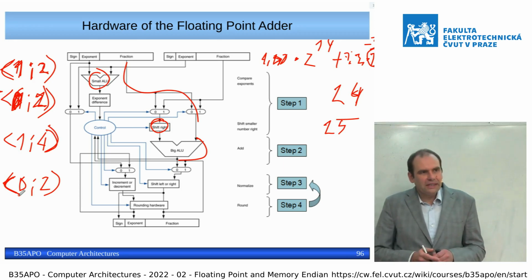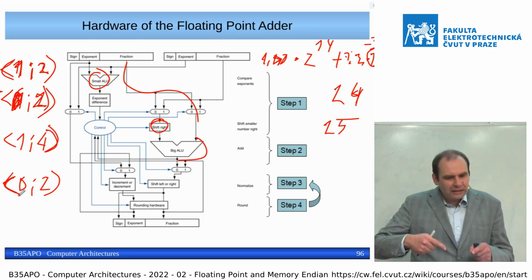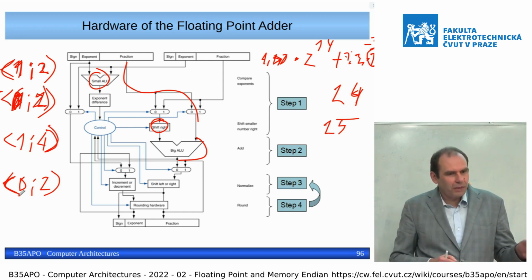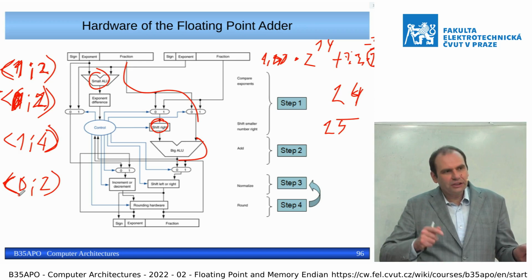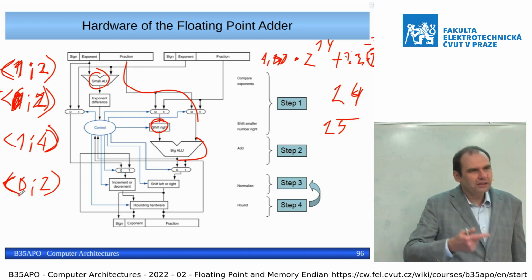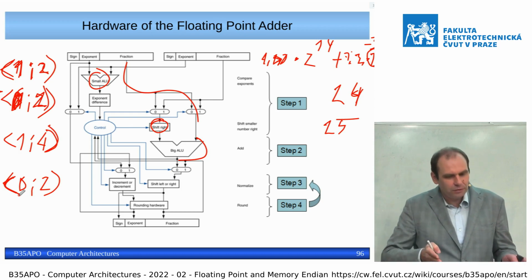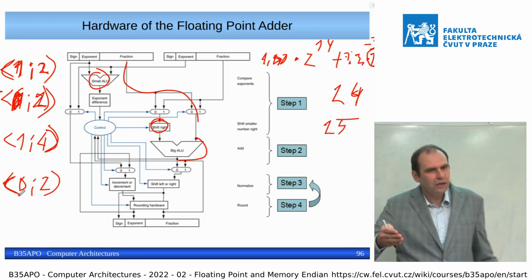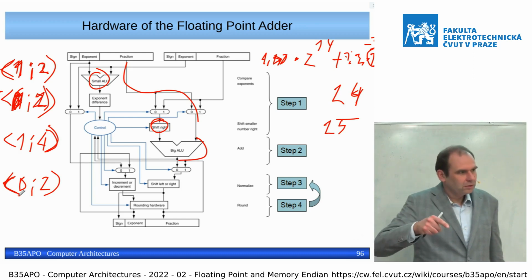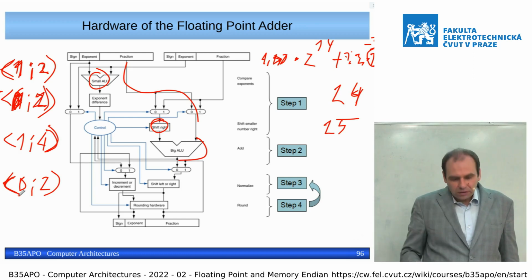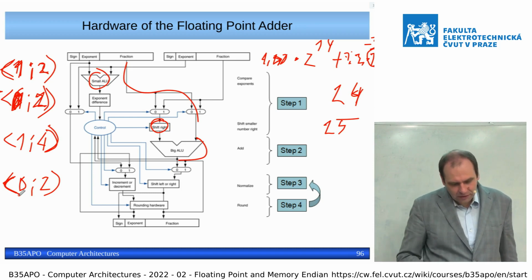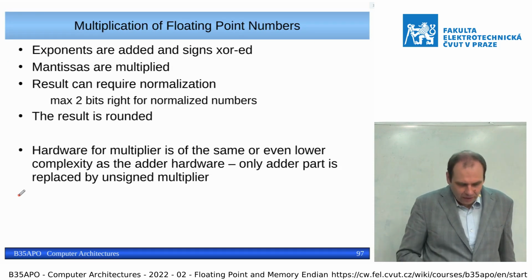And in this case, we need to multiply the mantissa so many times that we get it to the normalized state. And each time we multiply the mantissa by 2, to keep the arithmetic value the same, we need to reduce the exponent by 1. So this way we can get at the end the normalized number.